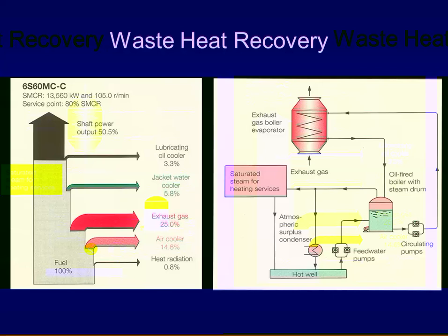So the newer engines with these big turbos, there's less heat for recovery. Typically anymore, I think you're above about 60 megawatt prior to getting into where you could efficiently do combined cycle. But there's quite a few ships out there in that power range.